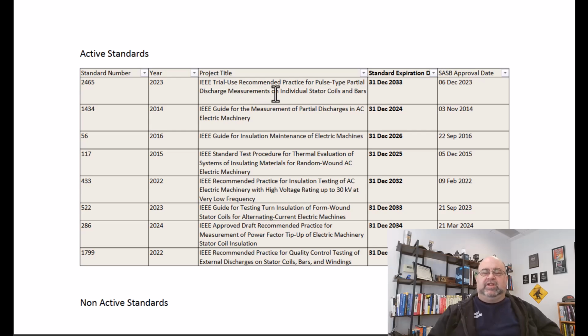So this is equivalent to the IEC standard that we use for the Baker instruments and Electrum, and the ones that have offline PD test. And there's some specific offline PD testers only for repetitive pulses. So these are the ones where you have your surge tester, you clip it on, and it'll also give you PD inception and extinction values.